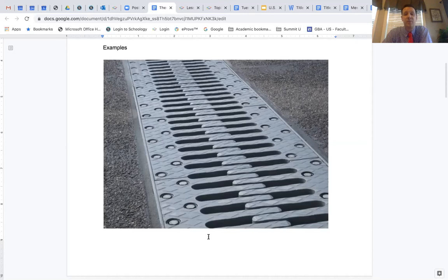So you have a little crack that forms in a roadway, and then water gets in, and then in wintertime, that water freezes. Well, we all know that water expands when it freezes. Well, there's no expansion joint built into that crack in the pavement. So what happens is that water expands and just expands out, and it actually cracks the pavement larger. And then it melts, more water fills in. If it freezes again, more water's in there, so it expands it even more, because there's no expansion joint. That material is not made to expand.